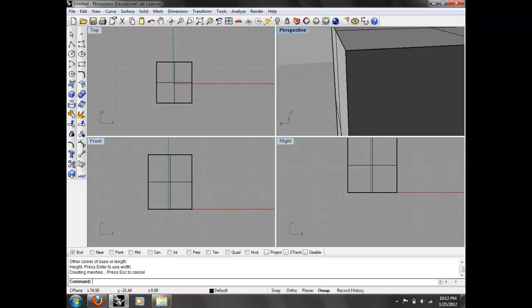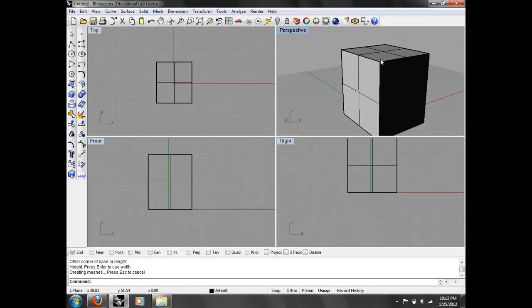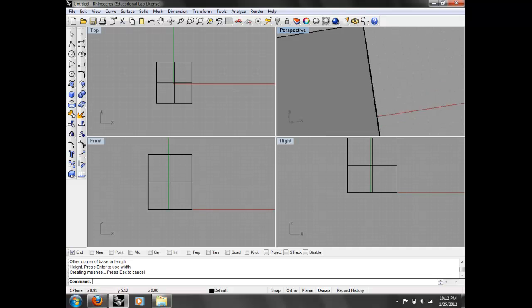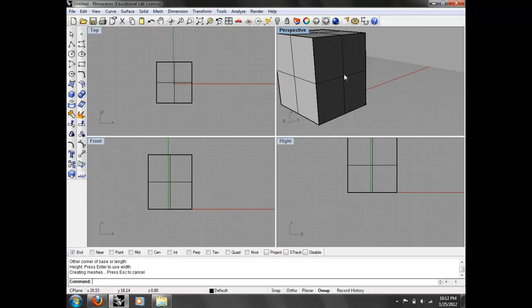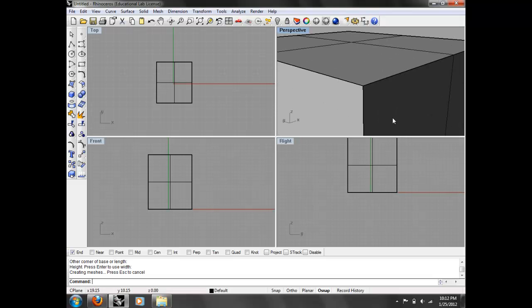And if you zoom and orbit, once you get really good at it, you can find exactly what you want. Panning, if you're in the 3D port, you hold the right mouse button and shift at the same time, and that accomplishes a pan. So I can pan, zoom, orbit, and I can find things very quickly in three-dimensional space. And you'll get very fast at this, very good at this. So pan, orbit, zoom.